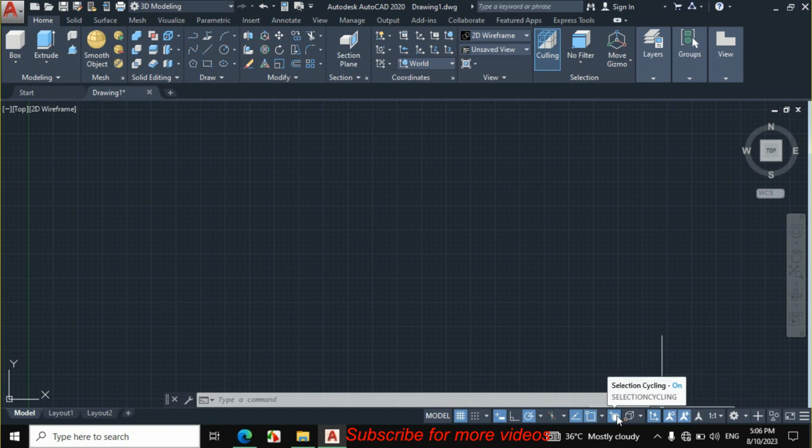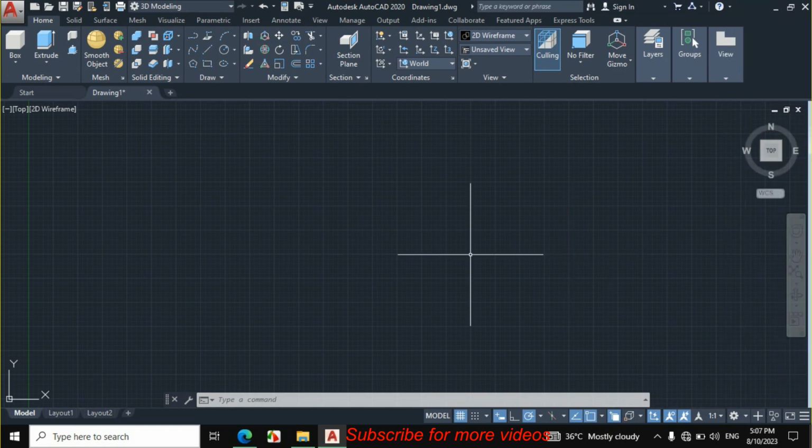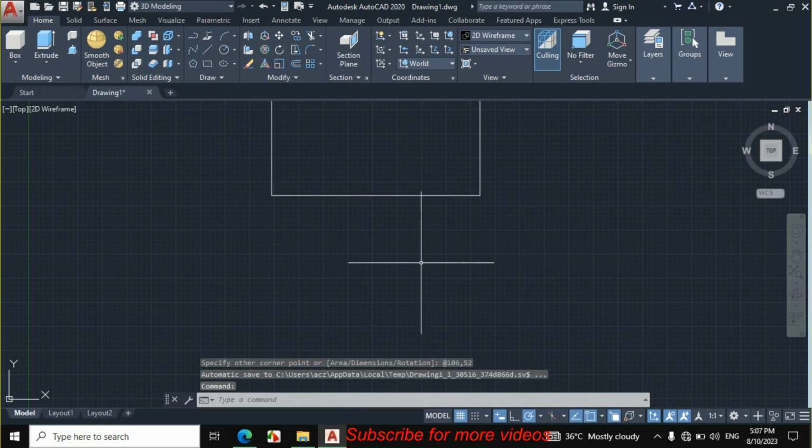If you do not see this option, selection cycling, then click on customization. From here click on selection cycling, and you will see this option. Let's click on this, so it will disappear from here. Then again click on this, so it will appear here. Now let's draw a rectangle. Click on rectangle, then enter a length of 106, then press comma, enter width 52 mm, enter. So the rectangle is made.